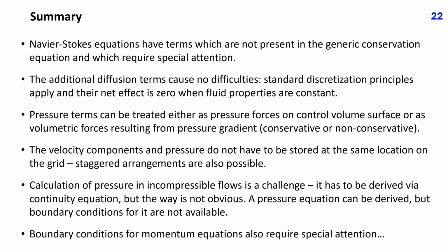Calculation of pressure in incompressible flows is a challenge. It must be derived via continuity equation, but the way is not obvious. A pressure equation can be derived, but boundary conditions for it are not available. Boundary conditions for momentum equations also require special attention, but this causes no difficulties.